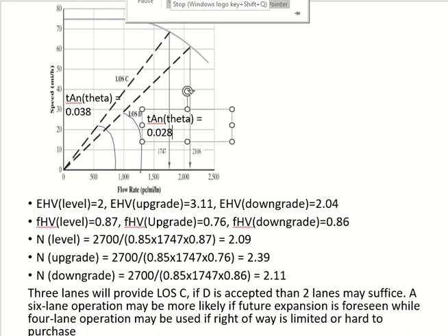It's upward and downward, right? So there are 2 directions of the same road. We don't do 2 lanes here, 3 lanes there. We are saying 3 lanes are required here and 3 lanes on the other side as well, even if it doesn't require. The 2 directions don't have any conflict between them. So even if one direction says 1 point something and the other says 2 point something, and you are rounding off to 3, then the other one should be 3 as well. It's common design practice. Got it? Clear? Not convinced? Wasting money, right?